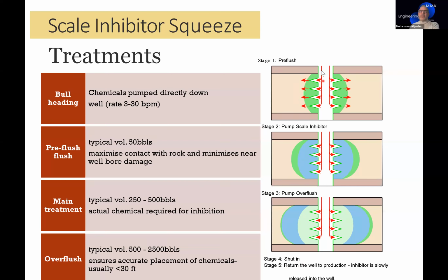So, what is the sequence of our process, and what is the sequence of our remedial action? Where to pump, how much we need to pump, what is the speed of pumping, what is the volume, where we have to pump, which formation, which perforation? Do we need any extra materials and extra solvents to pump, the direction of this pumping fluid, do we need any extra gel direction? So we have to put our plan very carefully.